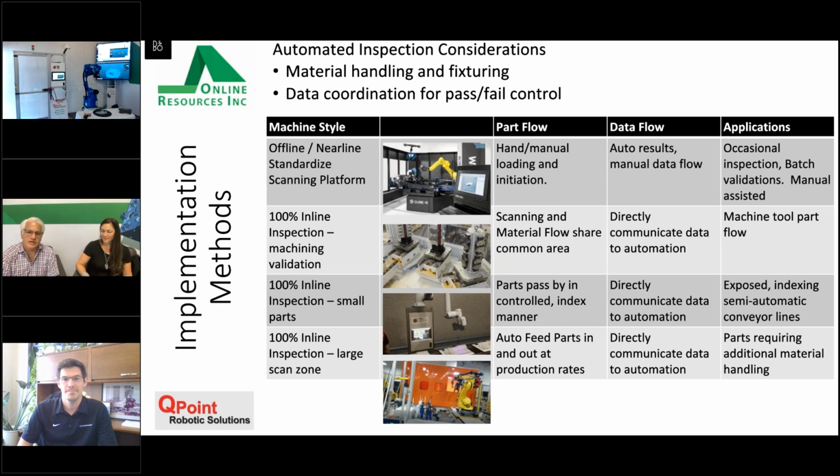Are there things behind the scenes you can get into? Of course. For the scanning application, there's some pretty interesting things in the background that you set up. There's a scan configuration file where you would teach the background and the standard clipping planes of the scanner. At a little more of an engineer level, you would set that stuff up in VX Elements, which is what the scanners work off of. You would save that, and when it runs, all you have to do is call up that file and it works.